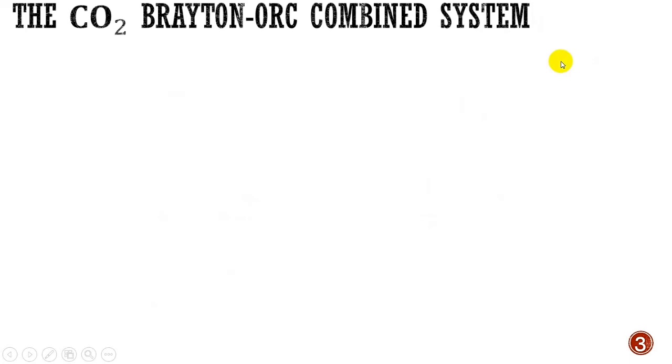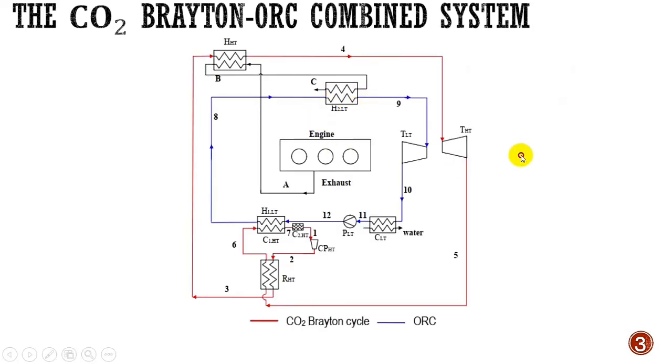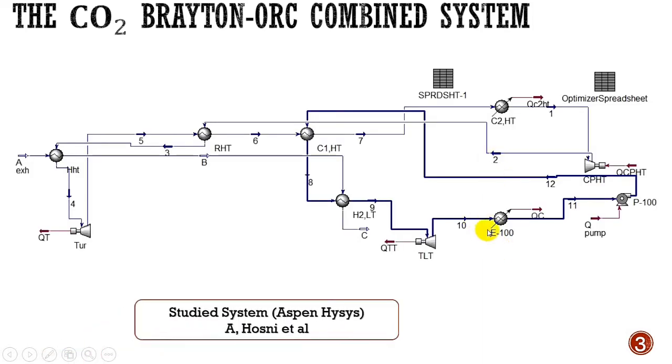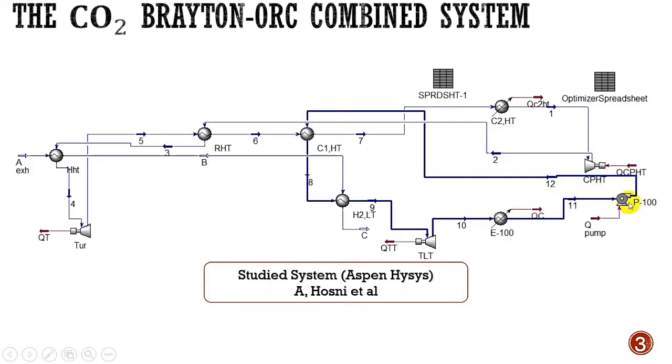The current work is about the combined Brayton cycle with the ORC, organic Rankine cycle. It's proposed to use the waste heat exhaust gas from a diesel engine. All this is simulated and studied by Aspen HYSYS, where the Brayton cycle here